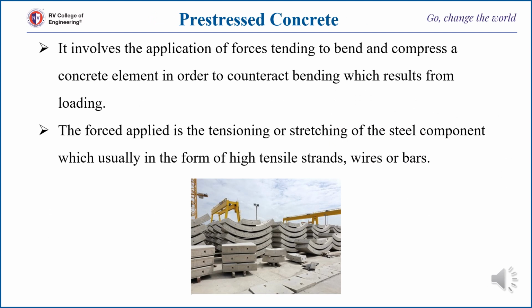Pre-stressed concrete involves the application of forces tending to bend and compress a concrete element in order to counteract bending which results from the loading. As we all know, upon loading the concrete, it will bend, so to counteract the tensile bending forces, we initially apply compressive stresses before loading the beam, so that the initially provided compressive force will be counteracted by the tensile forces.